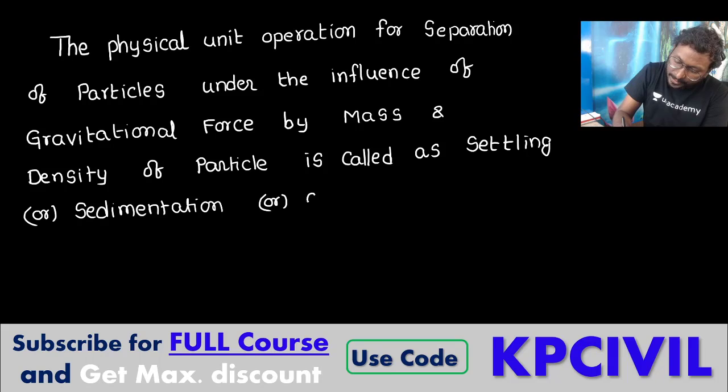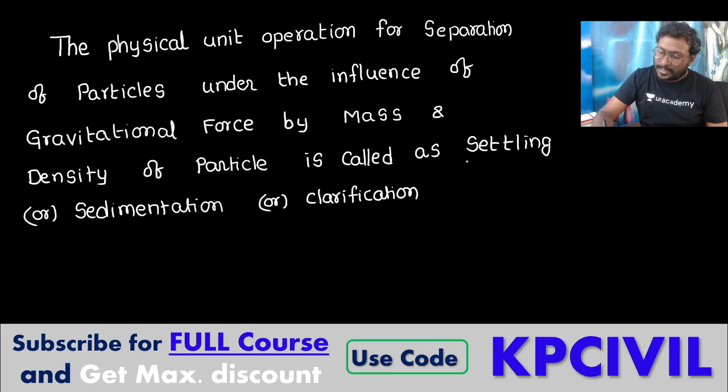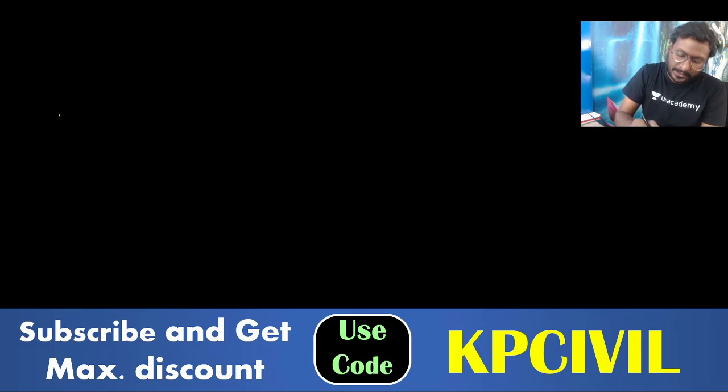Settling or sedimentation or the same process we consider as clarification. All are the same. We are not differentiating anything. All three words are the same: settling, sedimentation, clarification, in which any particle falls down, settles down under the influence of gravity due to their mass and density. That phenomenon is called settling or sedimentation.